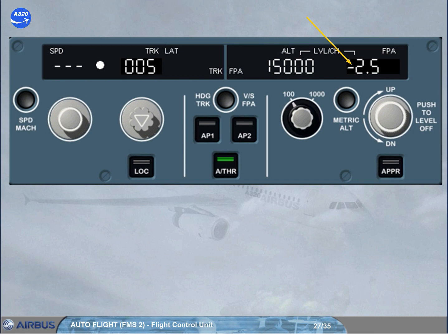To engage the Autopilot Flight Director Flight Path Angle Selected mode, we have pulled the selector knob for you. For training purposes, we wish to change the flight reference, and thus select the bird off, changing the basic Autopilot Flight Director guidance references from flight path angle to vertical speed.